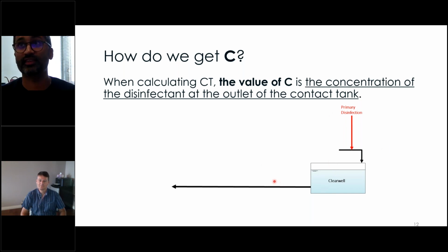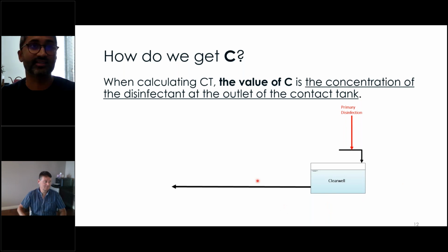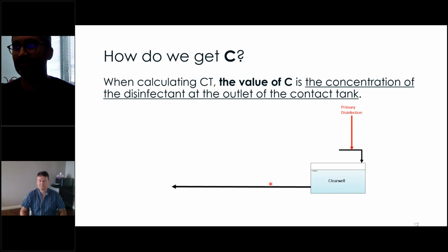But it is true, there's water that's now re-entering. So in a sense you're getting a longer contact time as a result of that, because water is getting more time to spend, and you're supplementing with chlorine. So you're getting more contact with chlorine. It would definitely increase your contact time, increase your CT. So in that case, that recirculation would have a beneficial effect in terms of disinfection for sure.